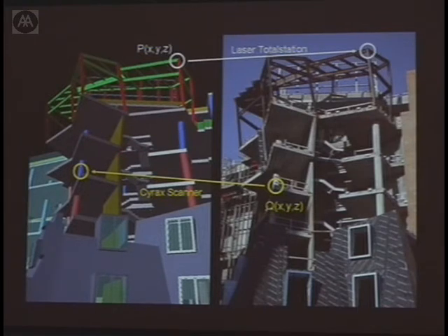In this case, you can see a reciprocity between the two. This is the instrument of contract. This is a contractually binding master model that you build off of, not the drawings. And we're basically using a laser total station to survey specific cardinal registration points on the site to plot our steel, or maybe to survey in place when we pour the slabs. We're going to pour in the geometry clips inside them to control the panels.